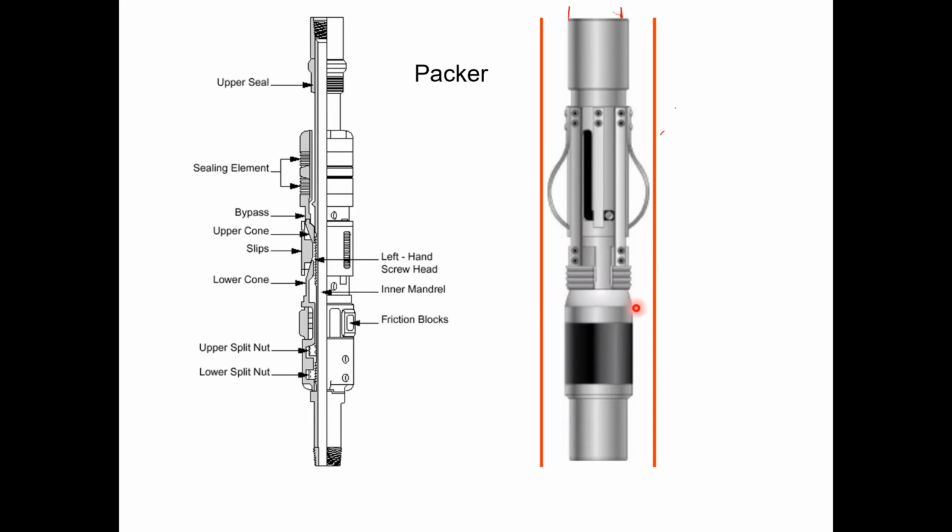And the same with this. And then after setting the packer, this elastomer will expand. In fact, the pressure will cause the elastomer to expand, and they will provide hydraulic sealing. This packer is called a tension packer. Why? Because it needs to be under tension.